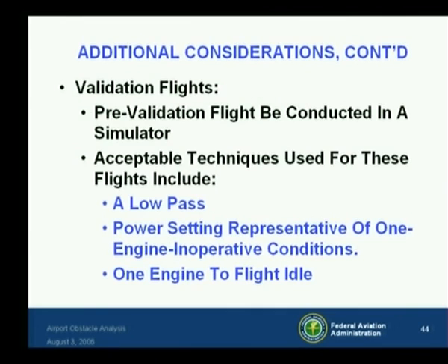Here's a couple more considerations. Consideration should be given to conducting a validation flight to confirm flight crew's ability to fly the actual special one-engine inoperative departure and to uncover any potential problems associated with those procedures, particularly if they differ significantly from the all-engine operating procedure or if terrain makes course guidance questionable at the one-engine inoperative altitude. Of course, none of these validation flights could be conducted as a revenue flight. That wouldn't work. If an actual validation flight in an airplane is required, it's recommended the pre-validation flight or flights be conducted in a simulator to simulate actual evaluation or validation conditions.